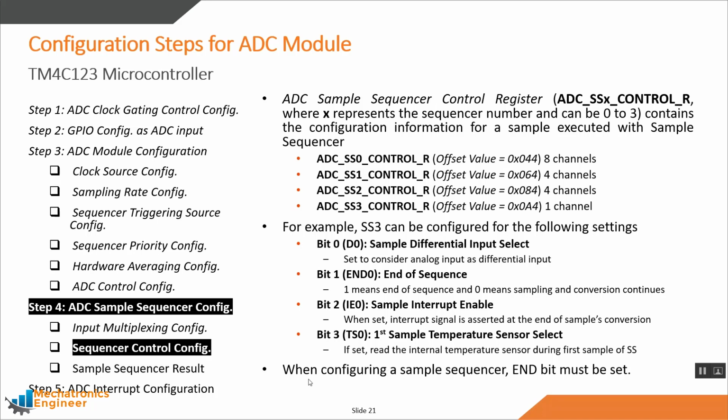It is very important to note that when configuring a sample sequencer, the end bit must be set, even if you are using a single channel with any of the sample sequencers.